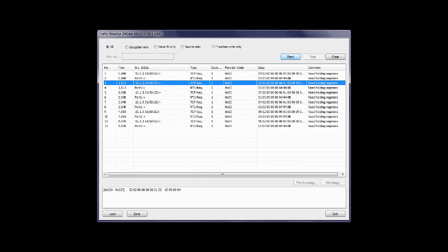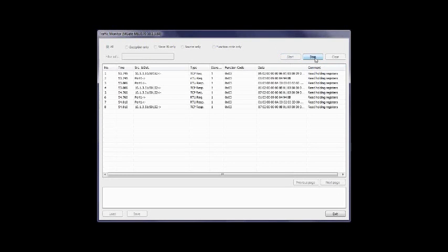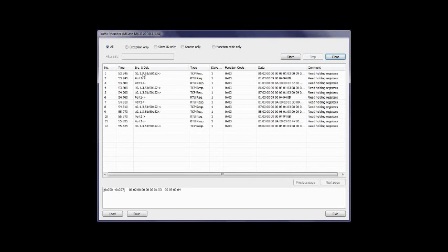Nice little thing here. I'm going to clear this, and let's fix the fault. What I've simply done is unplugged the cable to that PLC. So let me plug this back in really quickly. Let me give it a moment to come back and start polling, and let's run that test again. After fixing this, now you can see the correct thing that's happening here. Here's the request. Here's it being sent out the serial port, and here's that important response coming back from that attached device. And if you're a little curious, you can also see the specific request going. Here's the read request, and here's the response coming back.